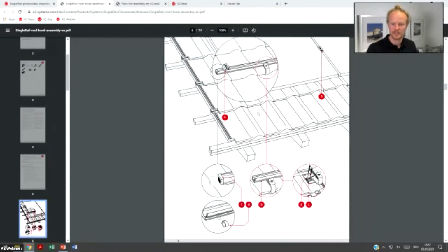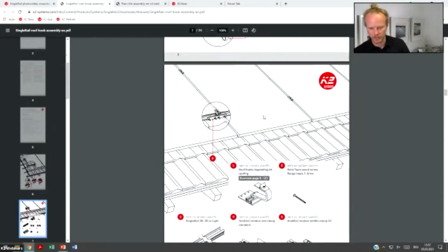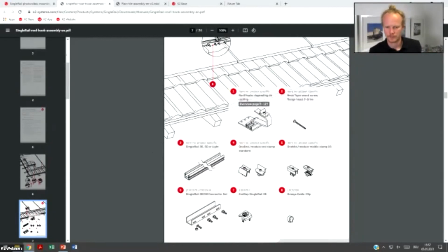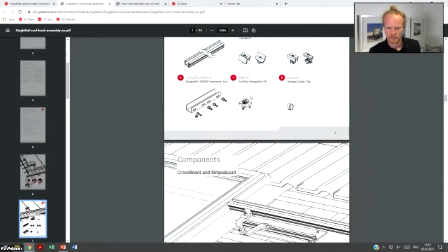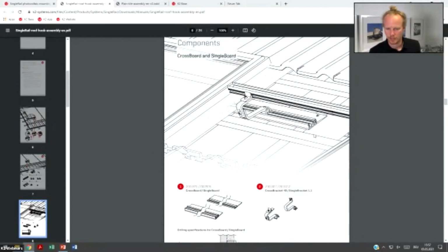All the information you find here will also come from the base report that you've made. Here we have another product that we did not discuss today, but it's suitable for when the position of the roof hook does not align with the rafter. There's effectively a long base plate that sits between two rafters and allows a little more flexibility of where the hook can be placed.